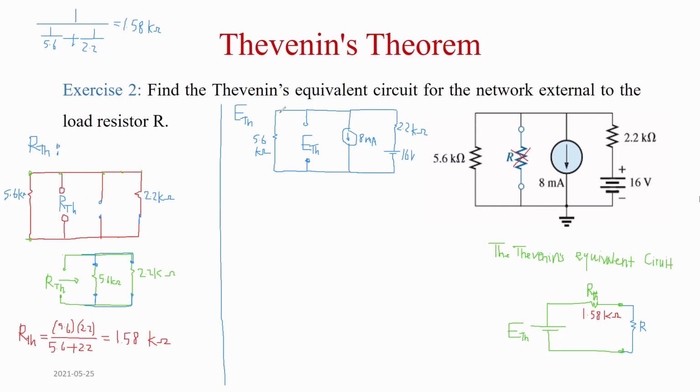So I'm going to find the voltage at this node, which is the same as this, connected, the same as this. They're all connected to one point, so there is one voltage here. I'm going to call this voltage V1, and this is the reference here, which is actually grounded, so V0.